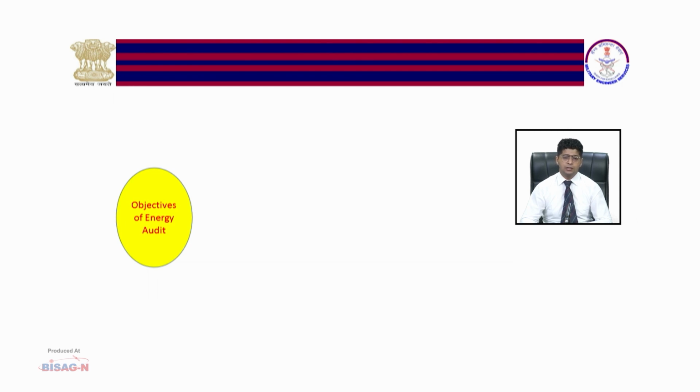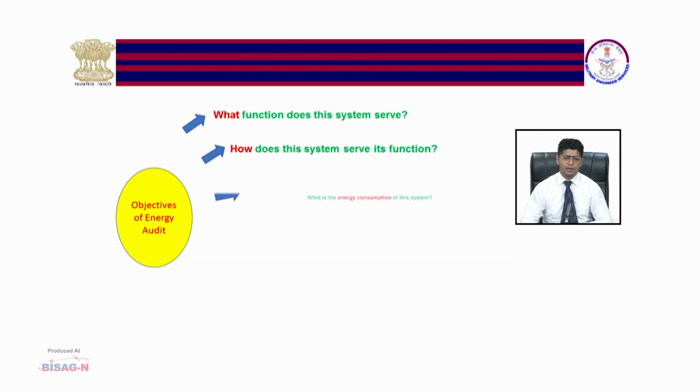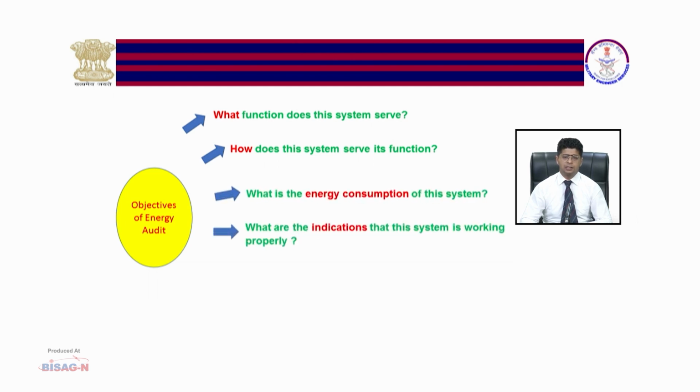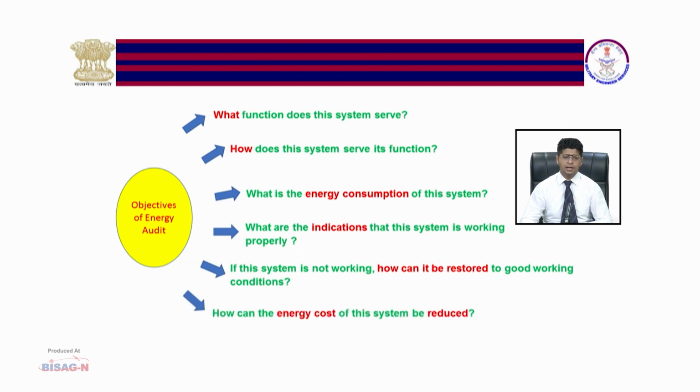The whole exercise of energy audit should revolve around basic questions. What function does this system serve? How does this system serve its function? What is the energy consumption of this system? What are the indicators that the system is working properly? If the system is not working, how can it be restored to good working condition? And lastly, how can the energy cost of this system be reduced?